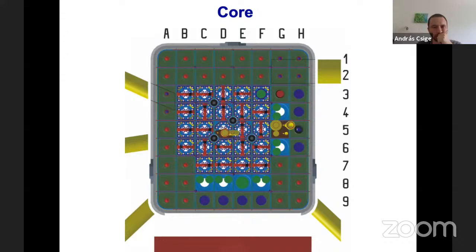Power level and power level rate of change is measured using neutron detectors around the core. There are 5 neutron detectors. One of them is used for control. The other 4 have safety functions. For safety, different detectors are used on low and high power levels. On low power, in the so-called source range, fission chambers are used. These sensitive detectors are blinded by high neutron flux. That's why you also have 2 less sensitive gamma-compensated ion chambers. Low and high power detectors are doubled for the required redundancy.